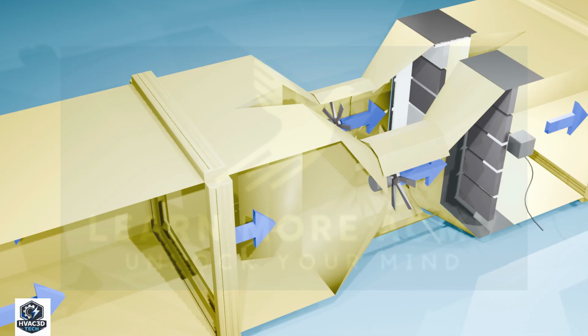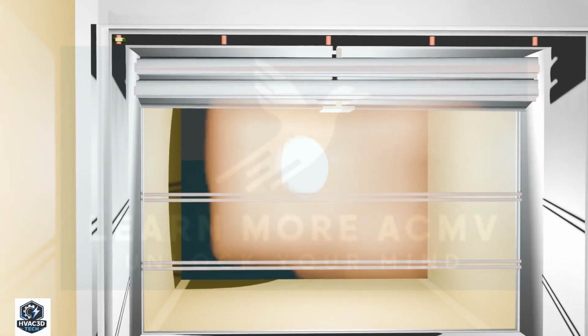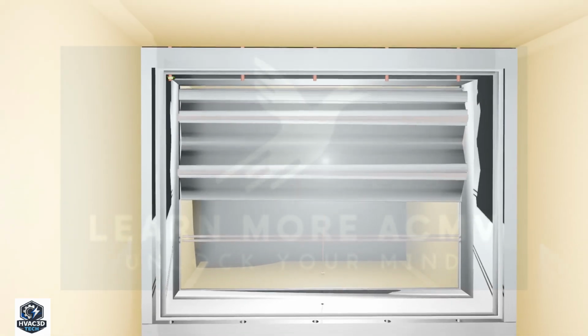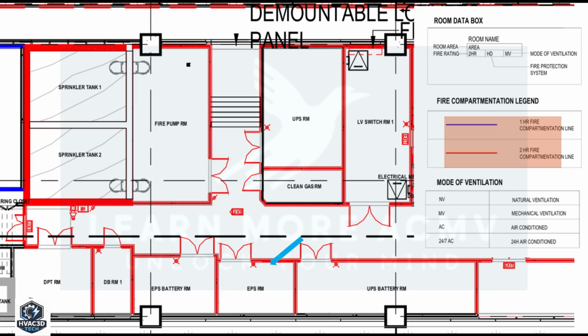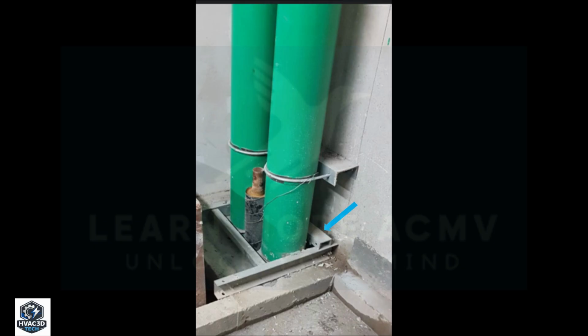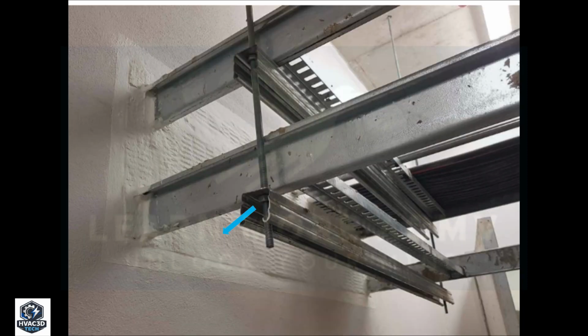Coming back to dampers, motorized dampers control airflow, while fire dampers are used to prevent the spread of fire from one compartment to another. Buildings are divided into fire compartments, often rated for 2 hours, as shown in fire compartment drawings. Although walls are fire-rated, services like ducts, pipes, and cable trays still need to pass through these compartments.